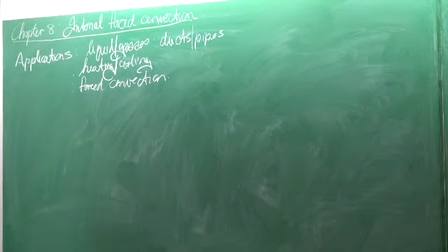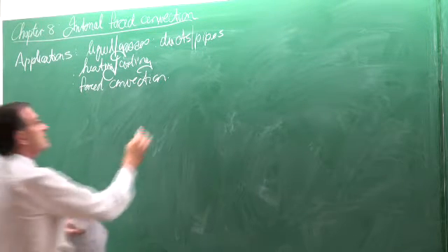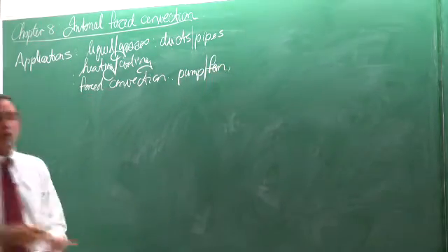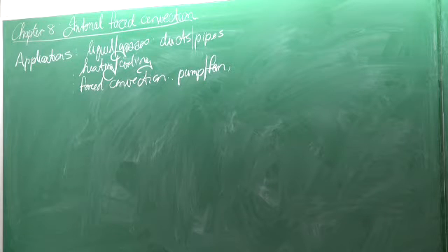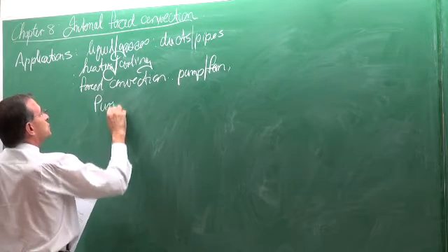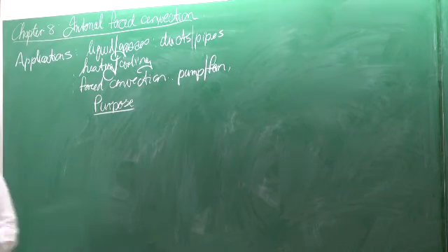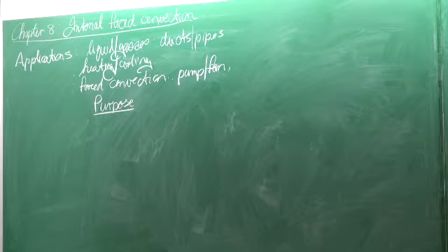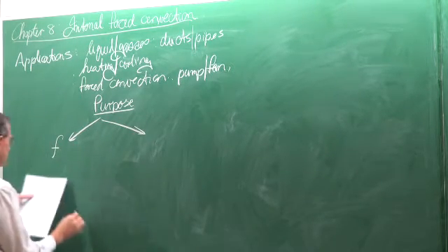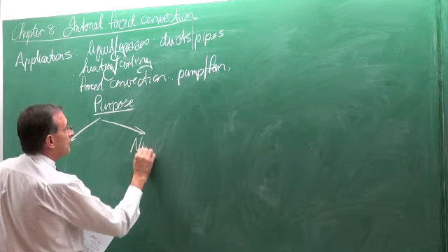What do we mean by forced convection? Forced convection normally occurs when we have a pump or a fan that will ensure that flow occurs through the pipe or the duct. It is not only the purpose in this chapter to look at the heat transfer, but in all cases we want to connect it to the pressure drop also. Therefore, we also need the friction factors. In general, we are always interested in the friction factors and the Reynolds numbers.